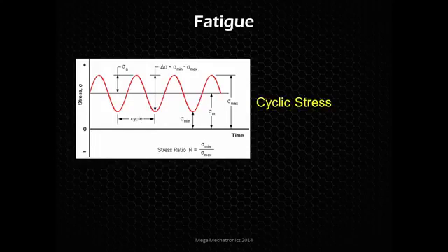So in this particular example, very nice, even stress, and you see it's being stressed on the tension side. So the space between the zero and the minimum of those valleys is a pre-tension, because it's not reaching zero, or it's not going into compression.